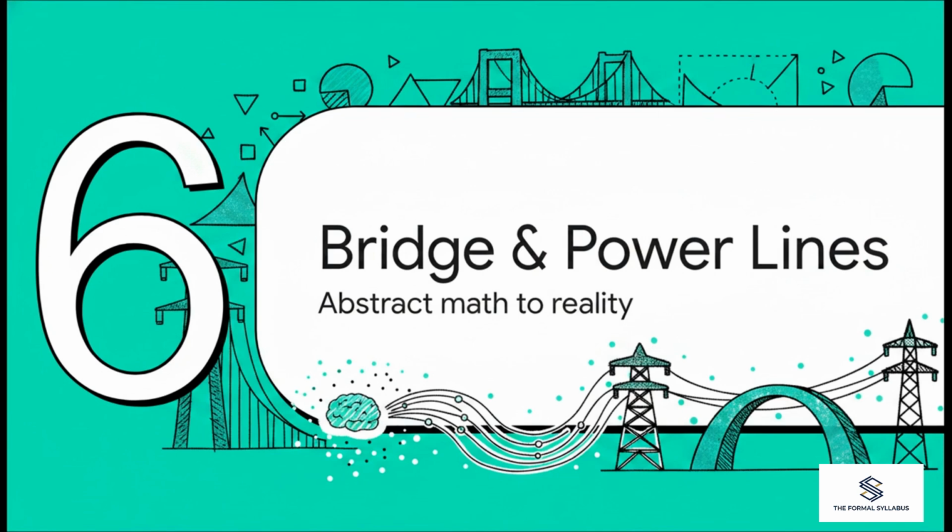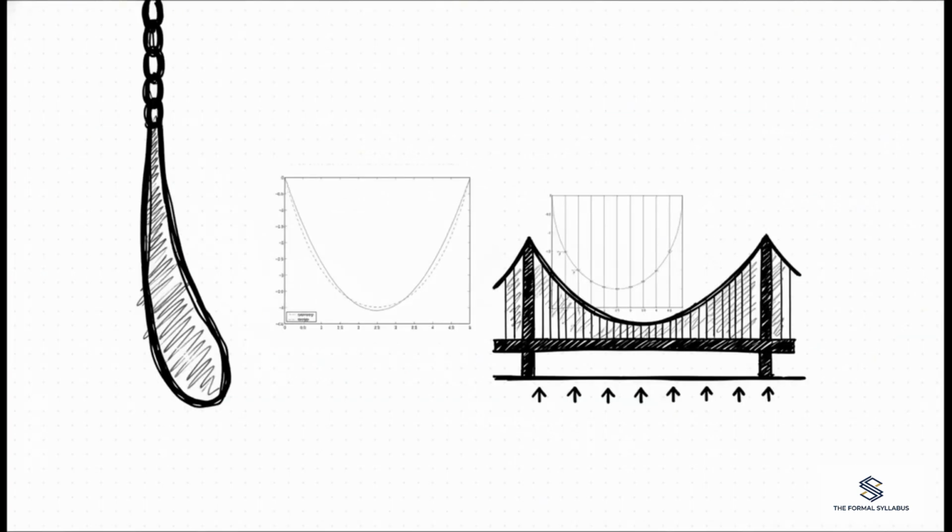Section 6. Bridge and power line design. From abstract mathematics to massive infrastructure. Now, when transitioning from a standard catenary chain to a massive suspension bridge, the physics actually shift. A suspension bridge's heavy roadway spreads the total weight evenly across the horizon, not uniformly along the cable itself. So, when we plug this uniform horizontal mass distribution into our parameterized solver, the mathematical shape transforms. It is no longer a catenary curve at all. The physical reality of the suspension bridge demands it becomes a perfect parabola.